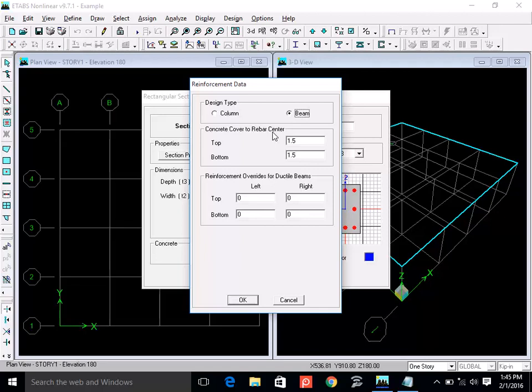In Pakistan, generally even bar sizes are available. So we rely on number 4, 6, and 8 for longitudinal reinforcement, and number 3 for the rings. But in the case of bridges, where you have huge sizes, we may have number 4 as shear reinforcement as well. Generally, number 3 is enough for regular buildings.